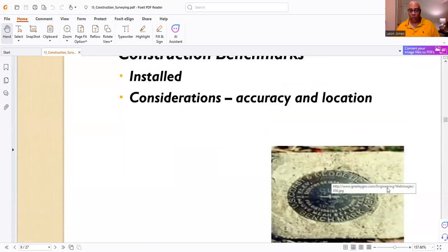Now, right here, when I was telling you about the dome, this right here is a geodetic dome. This is what surveyors use as a control point. Generally, you see a dome like this on a pair point of a bridge, or you could see them in the road. But these are points that establish everything that you're going to be dealing with, from road construction to subdivision construction, off this one point. And if you're running a traverse, you want to check right back into that point to check how accurate your survey is.